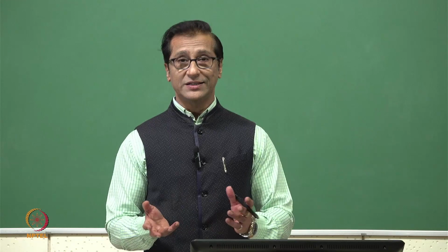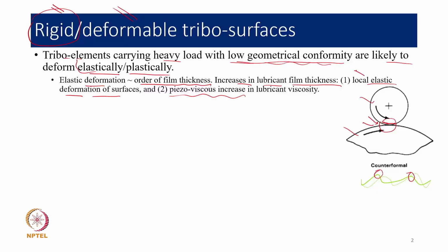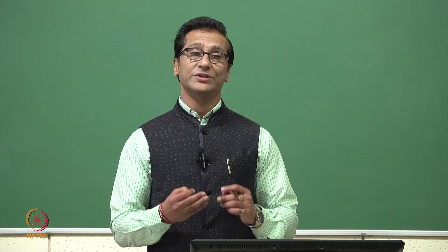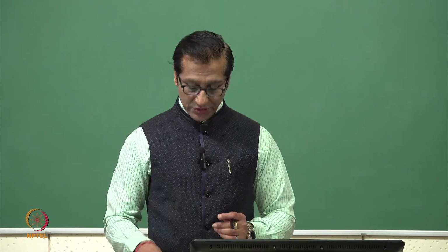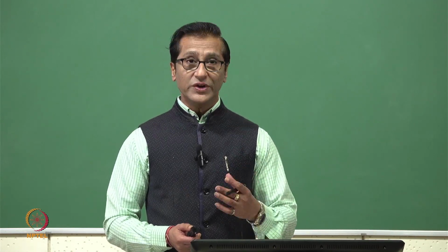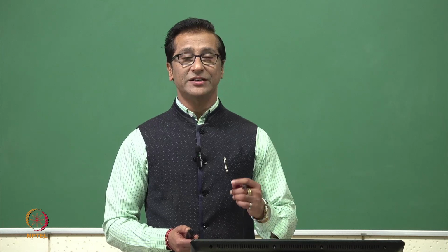So there are three different mechanisms. One is the hydrodynamic film thickness, which we learned in the previous lectures. Second is the local elastic deformation, which increases the film thickness. And third, because of the piezo-viscous effect, viscosity increases, which also increases the film thickness. This is very advantageous from a tribological point of view, but difficult in implementation.